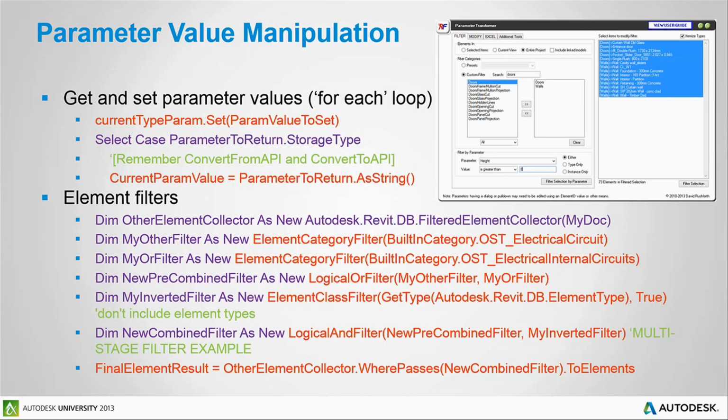There's the filtering in Revit, where you've got the filter options, it's just by category. Well, what if I don't want just all light fixtures, I want this specific light fixture that is of this specific type. Or maybe I want all lighting fixtures that are 2 feet wide. Well, all these filterings are not available within Revit in the filter command unless you go through and start creating a whole bunch of custom schedules and you're changing all the filtering and the things.